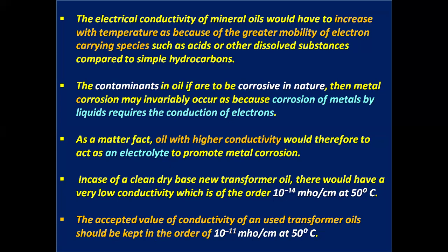The accepted value of conductivity of used transformer oils should be kept in the order of 10 to the power minus 11 mho per centimeter at 50 degrees centigrade.